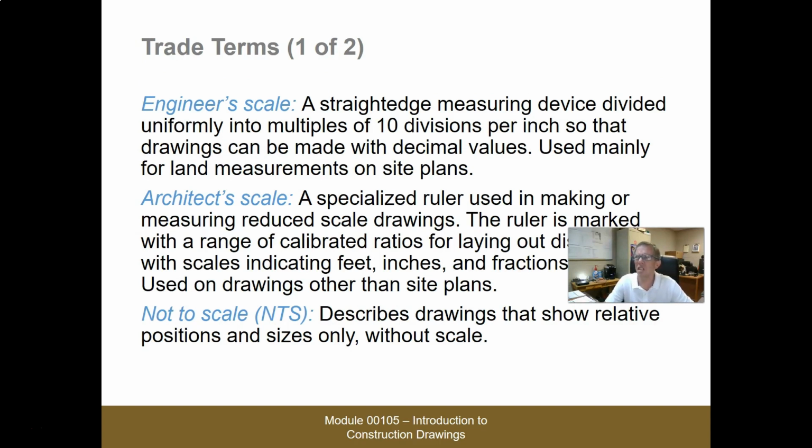And what is scale? Scale is where we want to take a building or anything to be built to a certain size, and we've got to scale it down where it will fit on a piece of paper that I can give to you, and you take and scale it up and build it into the real world as the actual size. When they scale it down, they'll put what they used at the bottom of the plans, and it may say 1/4 of an inch equals a foot, or 1 inch equals a foot.